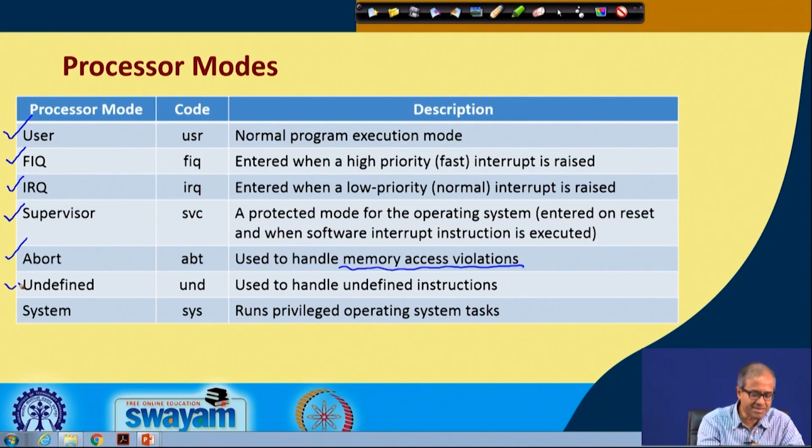And undefined is actually something which is kept for future expansion. Well, some instruction opcodes have not been defined, they are undefined. So, if by mistake you are trying to execute an instruction whose opcode is undefined, you get an undefined interrupt and the processor mode goes to the undefined state, UND.